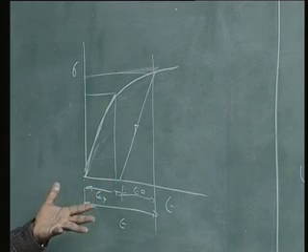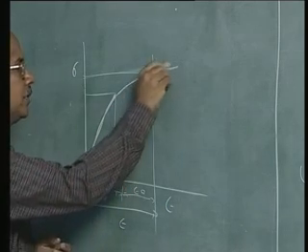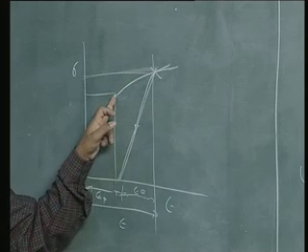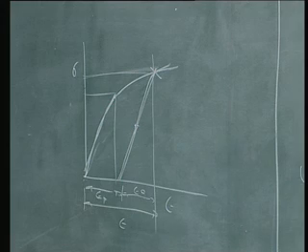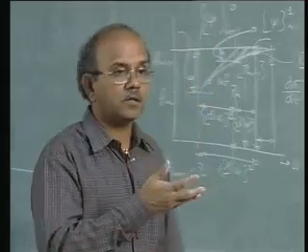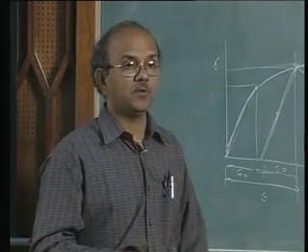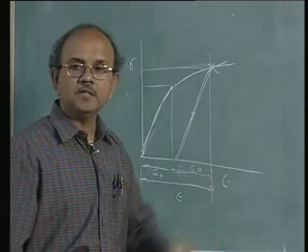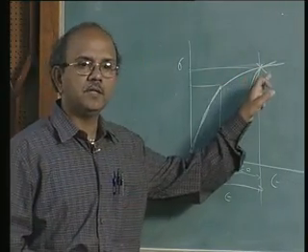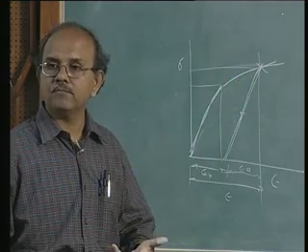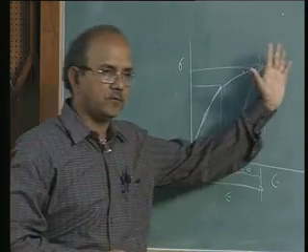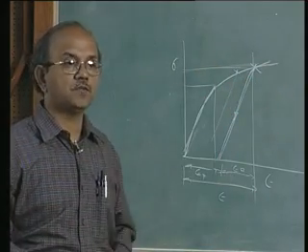Okay. And when I reload it, obviously you know that when I reload it from here, it goes and catches the curve there. And so the yield point is now moved away from this position, which I will call the initial yield point, to the current yield point, which is at this point. So the most important point is that the yield point, or yield strength, is not a constant when we do an elastoplastic analysis. What is usually stated as the yield strength of a material is, I would say, the initial yield. In fact, the stress strain curve is the locus of yield points. Every point here after I move from the initial yield strength of the material is a yield point. Is that clear? So if I had unloaded it here, then that would be my yield point. So it's a locus of yield points that we get, and so it defines the flow of the material, so it is called the flow curve as well.